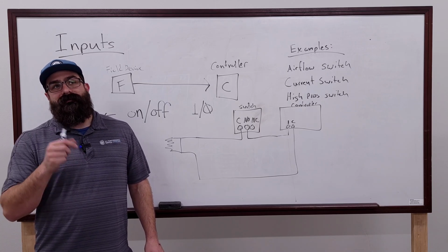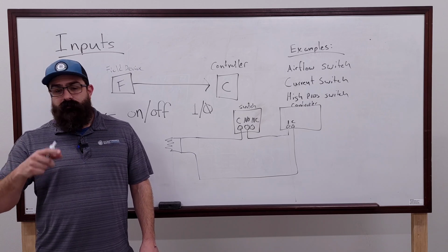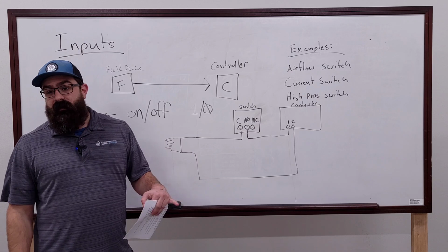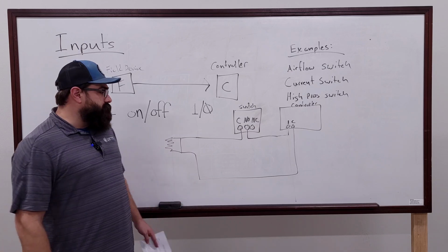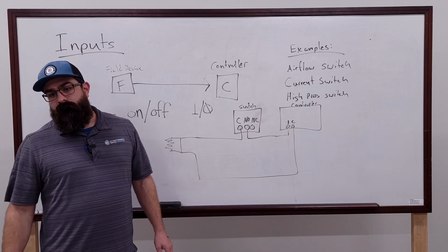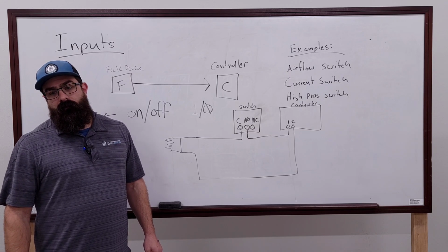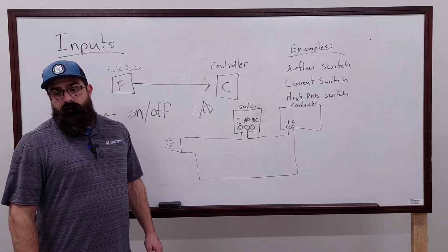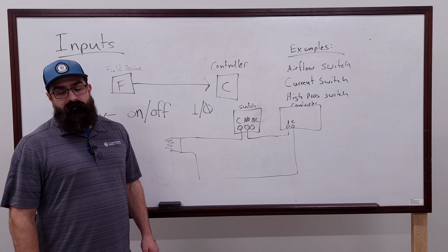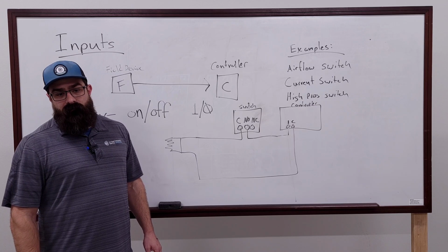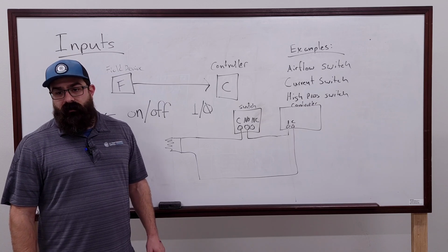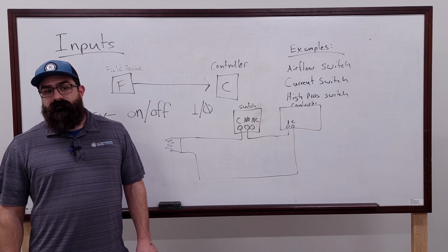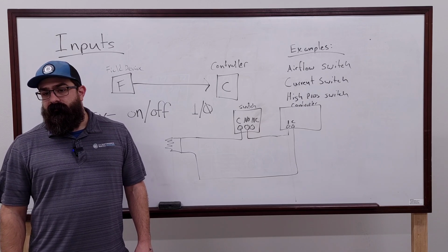Basically, that input does not have a source of voltage to push through this set of contacts to be able to recognize that a closure has been made. So, how much do we see that style versus? Rarely. We rarely use them. And the Distech and Honeywell don't have that. Don't need them. So both Distech and Honeywell, you can set them up with a dry contact. No need. Johnson Controls can be a dry contact. Most stuff will work dry contact.